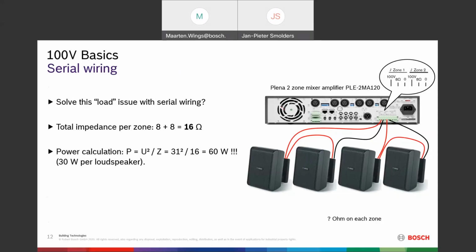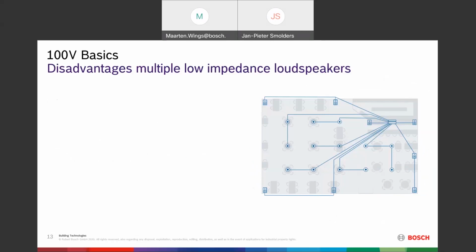So this amplifier will not be able to deliver the full current that is required for 120 watt. As a result, you will have in total 60 watt. We divide it over 2 loudspeakers, which means each loudspeaker can now deliver only 30 watt. So the efficiency of the loudspeakers and connections to this amplifier goes down drastically. This is also not a really good solution. You have to be really careful what exactly you are doing, because now you will have less power than the amplifier is actually made for.